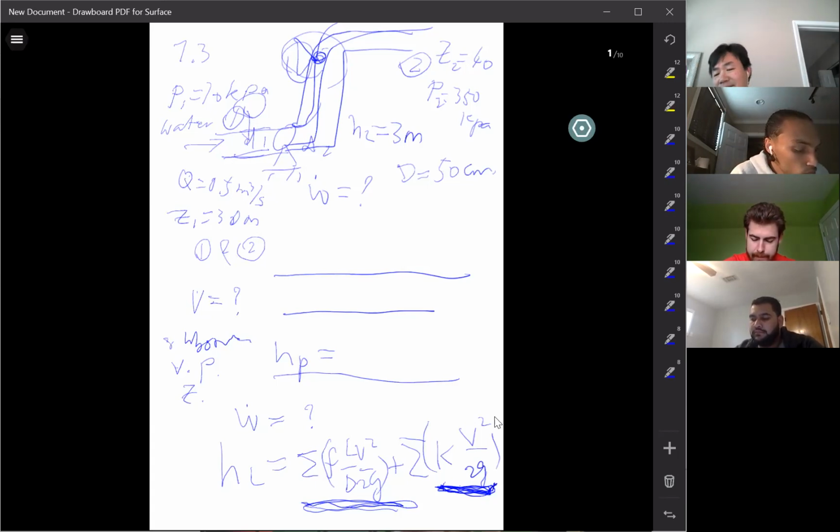You need to know the velocity associated with the portion of the pipe you're looking at. Also the velocities associated with the components, for each K. Each component has a velocity passing through it. So K times the velocity passing through that component gives the loss of the component. That makes sense?